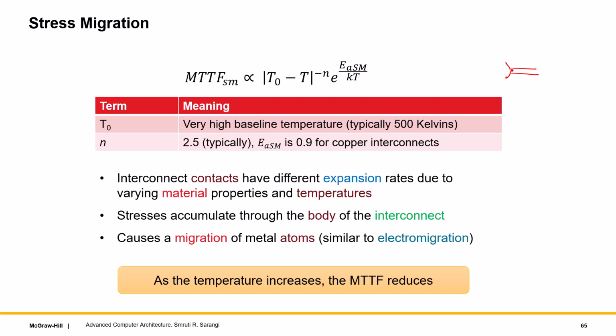That will create some amount of thermal stress, which can then migrate throughout the body of the interconnect, because it could be between two contact structures. Ultimately, stresses lead to cracks, so stress migration will essentially lead to atomic migration. You'll again have thin and fat regions and so on, and cracks, and finally the wire, especially near the contacts, will break down.